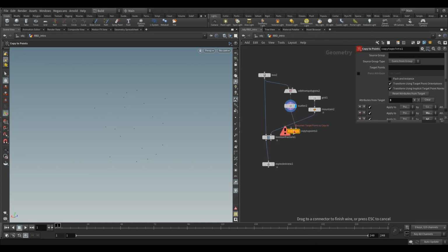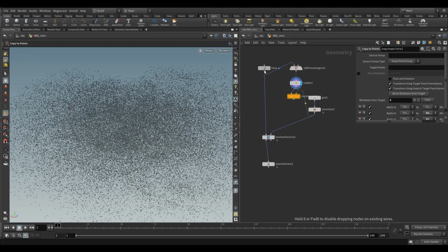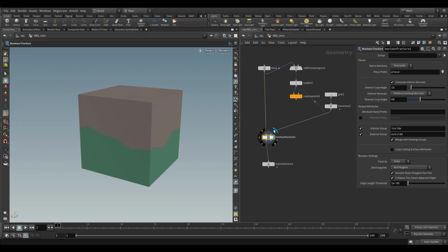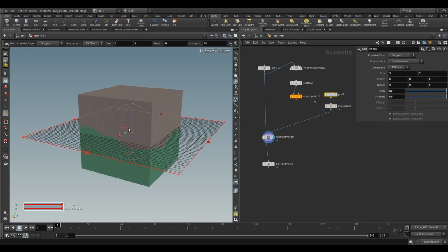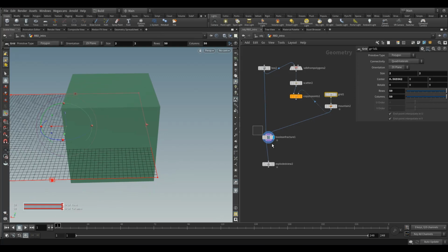And then geometry in there, points in here. Before I do this, I just want to demonstrate these booleans. They are really good. You get some really nice results, but they can be slower, and they can also fail quite easily. So if I move this grid over, you'll see what happens there. If any open edge is within your cutting geometry, then it will fail.